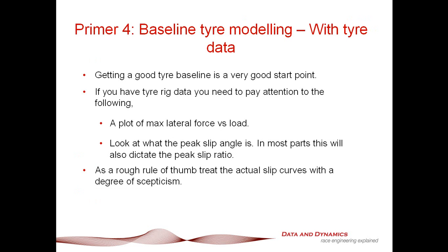Primer 4, baseline tire modeling with tire data. Now, this is something I get asked about an awful lot. Okay, we've got some tire test rig data. How do we incorporate it into our tire vehicle modeling, and what bit of the data do we look for? What you want is the plot of max lateral force versus load.